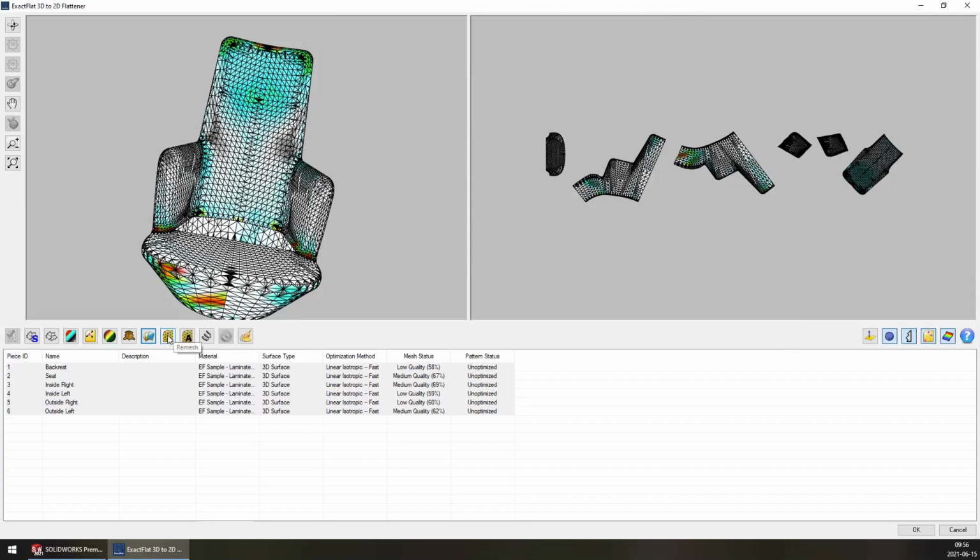With the uniform remesher, we typically set a target vertex count and we set some fidelity constraints, and these are changed. We change these in the ExactFlat options, and we'll look at how we change these options tomorrow when we look at the ExactFlat options. So with this one, we set a target vertex count, and the uniform remesher will remesh to that target count.